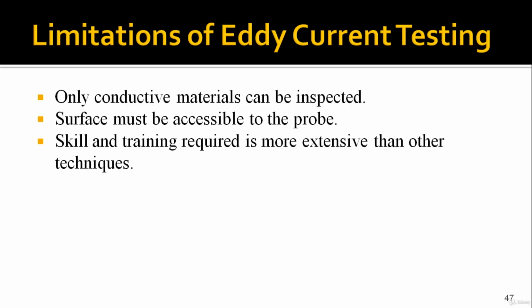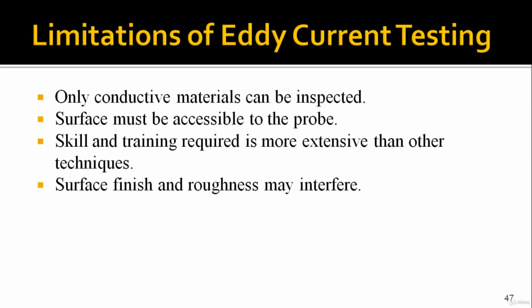Skill and training required is more extensive than other techniques. Very good skills and training are required to conduct the examination, because very complex and very sensitive components are involved in eddy currents. Surface finish and roughness may interfere. If the surface finish is poor, or there is roughness in the product, it may interfere with your results because the method is highly sensitive. So again, this is a limitation.